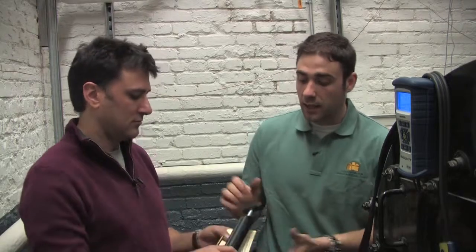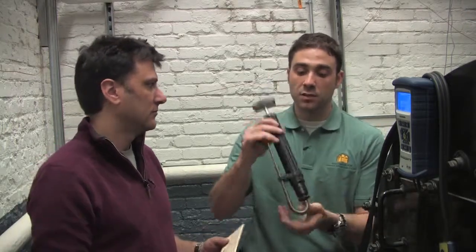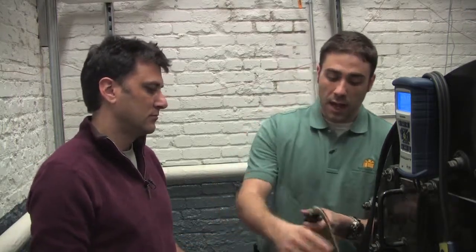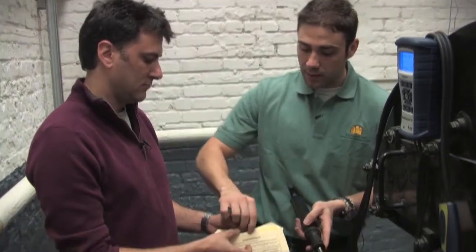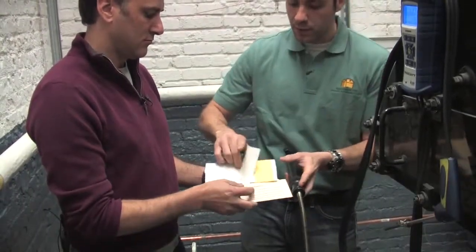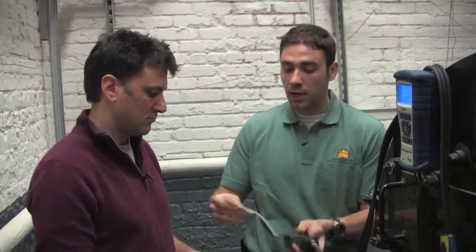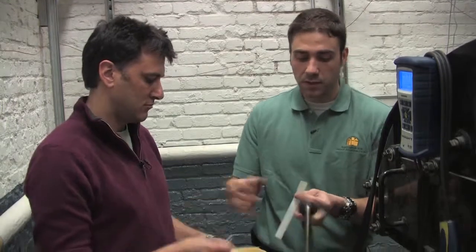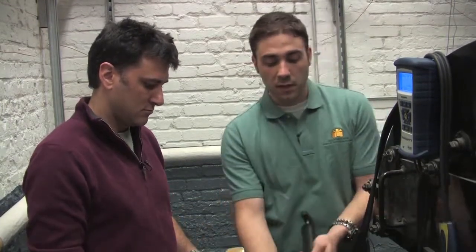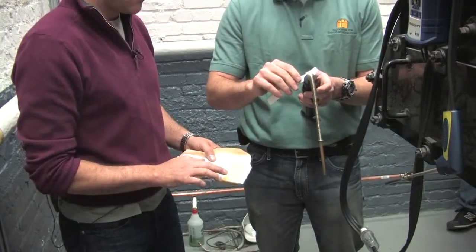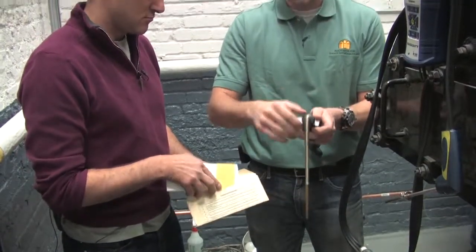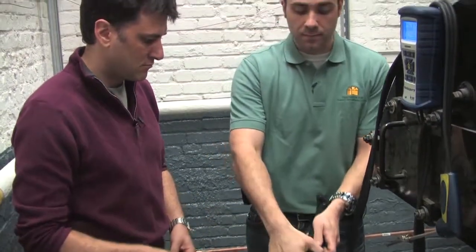So taking the little smoke spot tester, we have a little pump, and what we have is filter paper. Inside this little packet here, there is some filter paper. We have a sheet here, and we can pull it out, and we can do multiple tests with this. So we break off a little piece, I'll give you this one. And what we can do is a little clamp. This little nut adjusts, and we can open it up and insert the filter paper into the little slot, and we'll close it down.